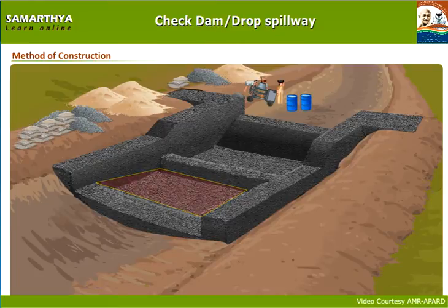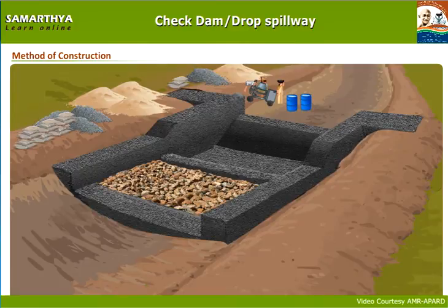Fill the center place of F1, F2, G2, G1 with 225 mm thickness stones which shows toe wall and at the center portion of downstream cutoff wall, and construct loose apron.